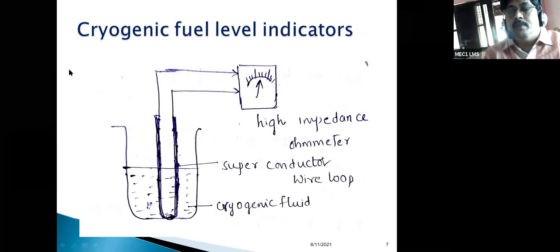This indicates that the air pressure is equal to the liquid pressure at the bottom, shown on the pressure gauge at the top of the bubbler tube. This is the hydrostatic pressure of the liquid, which is proportional to the height of the liquid in the tank.